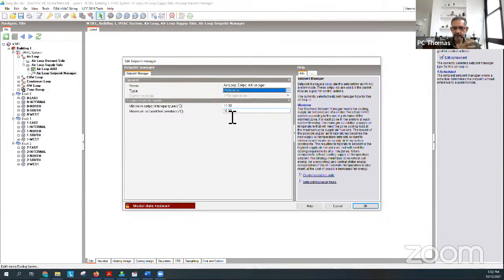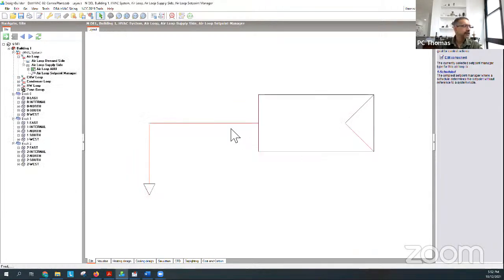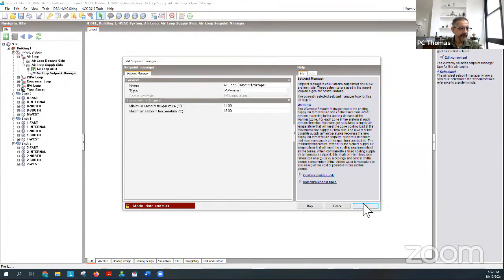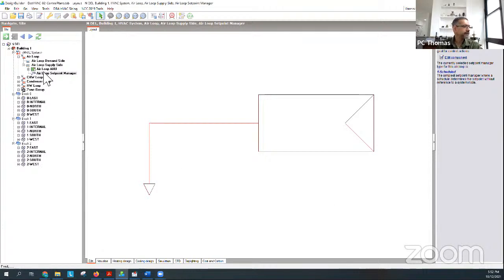can actually include the heating coil performance in the AHU, and we might have 20, 29. So it will move the temperature as required to what is needed. So for heating, it will do that. This temperature range is good for a cooling only type system. So the maximum supply air temperature, let's say instead of 16, we can make it as high as 18. Okay, so that's what I've got. That's fine, and I'm going to leave it at that.